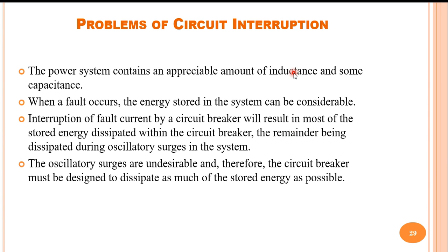The stored energy in the inductance and capacitors is mainly dissipated in the circuit breaker, but some remaining amount of energy is dissipated as oscillatory surges in the system. These oscillatory surges are undesirable, and therefore the breaker must be designed to dissipate as much of the stored energy as possible.